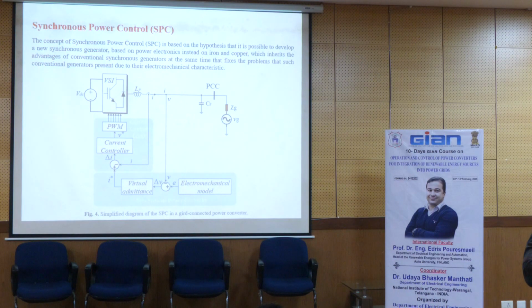Okay, let me say it differently. In the previous chapter, we learned how to use the PI controller. We saw that by the PI controller, you can measure the reference current and compare it with the injected current, and we can tune the controller and, based on that, inject active and reactive power and compensate the harmonic current components. Okay? So it means that whatever we want, now we can apply to the controller and obtain.